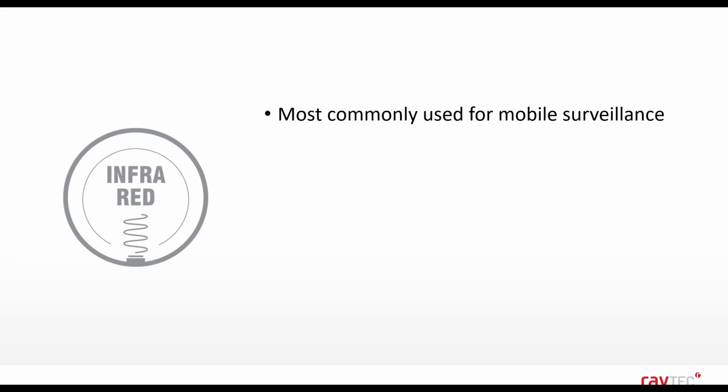But we also actually offer lower down on the wavelength, so 730 nanometers. Now, I don't know if I've specifically worked on applications where these towers have been used for ANPR type applications, but if that were the case, then perhaps exploring options within the lower band wavelength would be quite suitable, especially if you're looking to achieve through windscreen type applications where you're trying to see inside of vehicles.